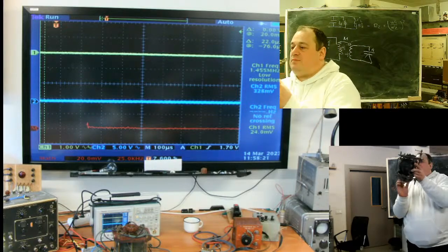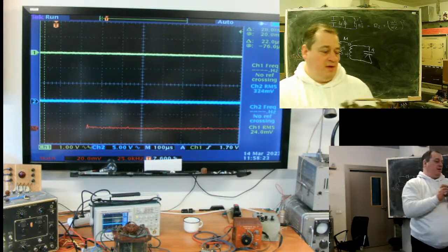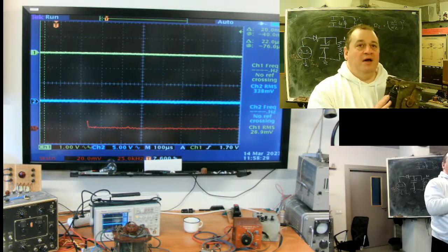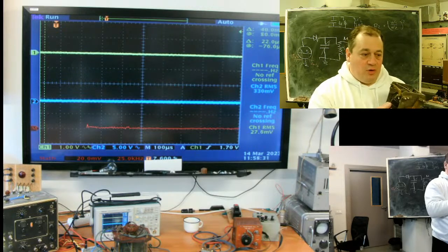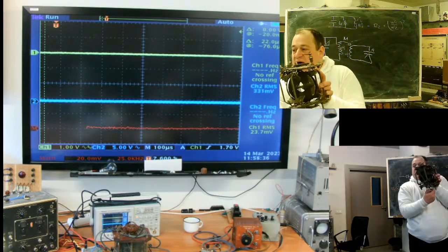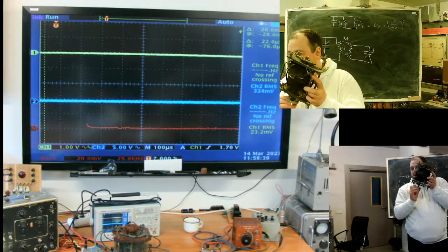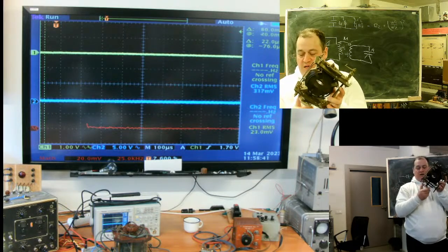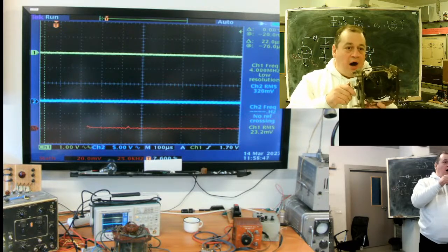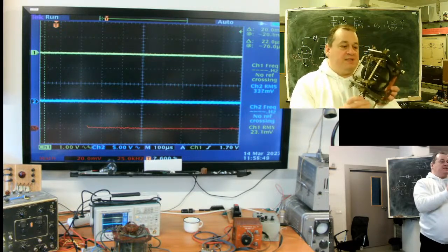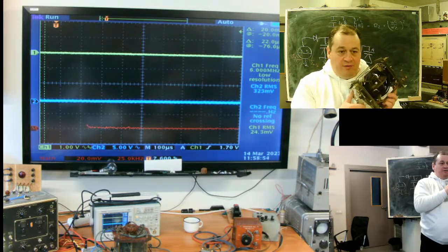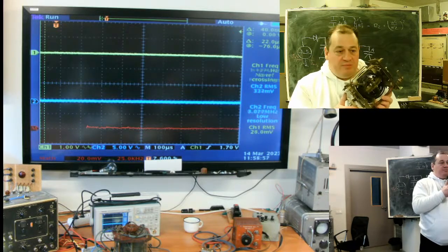The idea is that with rotation it changes coupling between the coils. Resistance and inductance remain the same. Coils are the same. Nothing changes in the coils themselves. But it changes the part of the flux coupled with the inner coil. This allows changing mutual inductance without changing other parameters of the network.